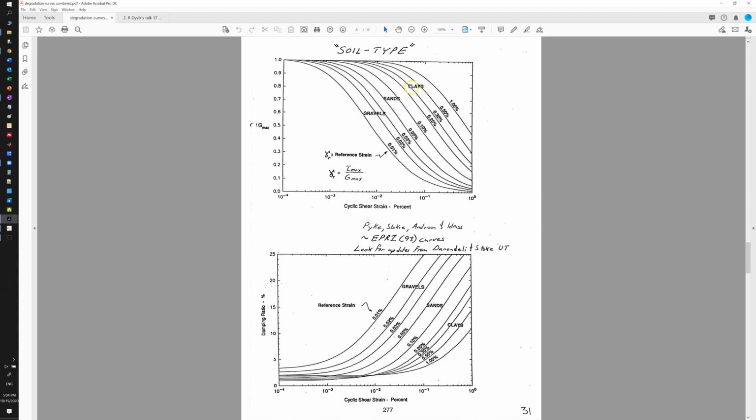So pretty much, you have a spectrum of different soils and how the shear modulus would change. It is highly soil dependent. So you compile all the data with the clay, sand, and gravels, and also the damping ratios. Again, nothing here is site-specific data.